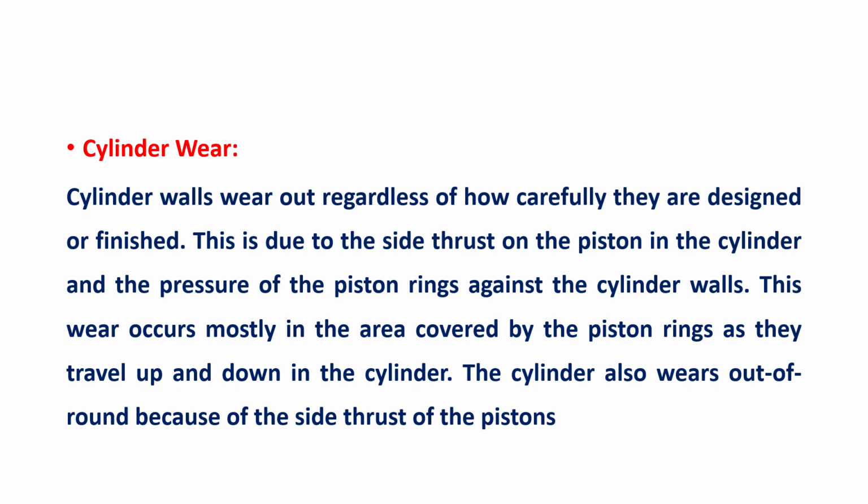You can also carry out inspections. When the wear ridge is deep and it is not possible to remove the wear, we have to inspect the cylinder bore now and then. Once the pistons are removed, the bore can be inspected for wear with the help of a cylinder bore dial gauge. This has to be done in order to ensure efficient working.